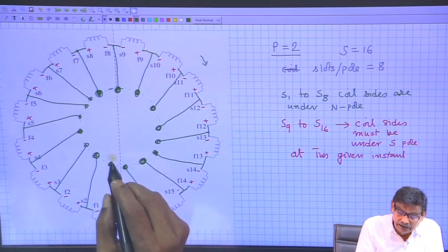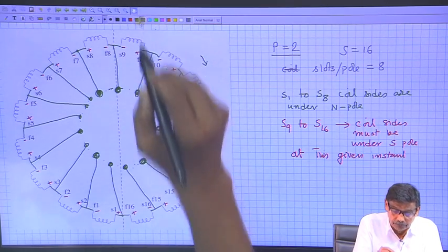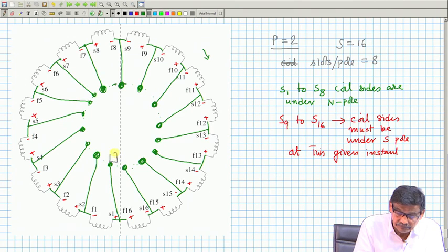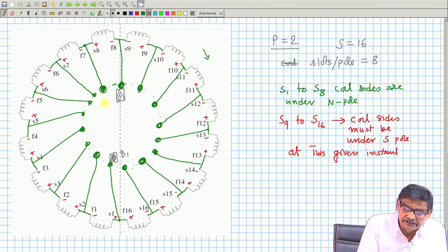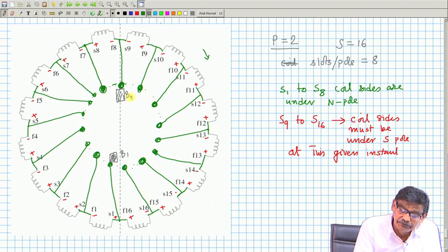Then what I will do? I will put 2 carbon brushes, which are fixed. Where plus plus has come, I will call it B 1, and where minus minus has joined, this is also a carbon brush. It is positioned in such a fashion that this copper strip will be touching this whenever it moves past, and this is B 1, this is B 2 carbon brush, and these two I will say are armature terminal 1 and armature terminal 2.